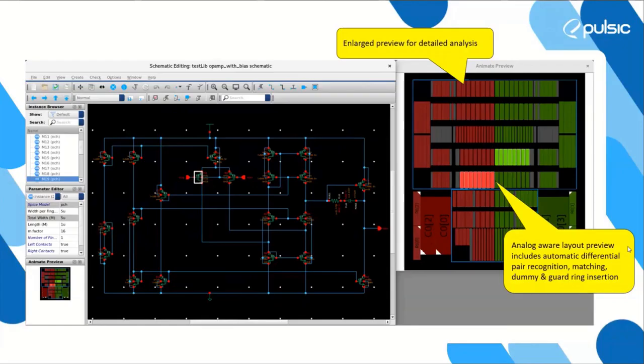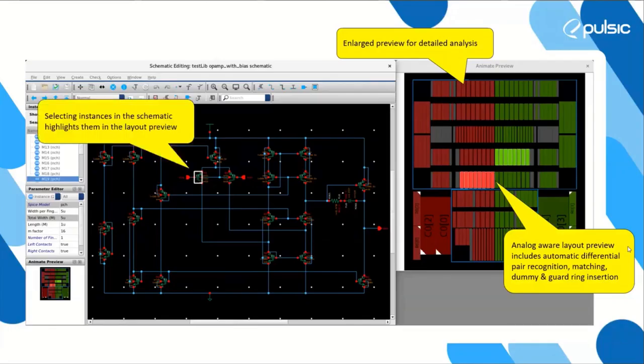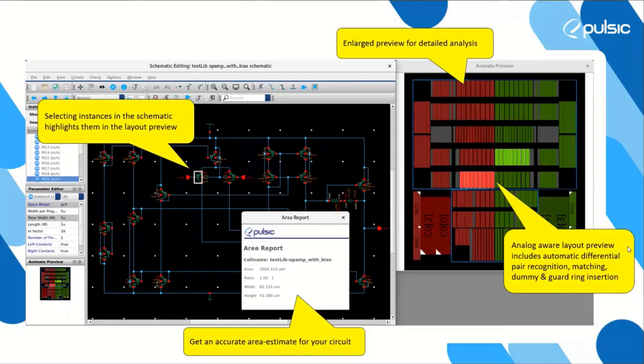And it's recognized, the picture is showing that we've highlighted one of the instances there in the differential pair, and it's placed those in a typical cross-quad pattern in the center of the design. And you can also get, at this level, an accurate area estimate for your circuit.